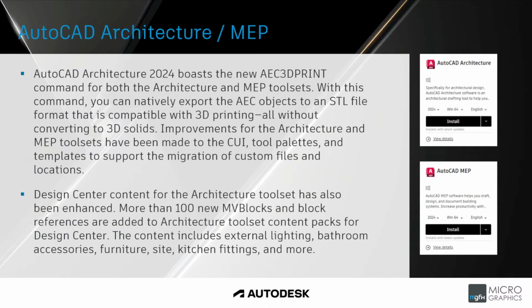AutoCAD Architecture and MEP. AutoCAD Architecture 2024 boasts the new AEC 3D Print command for both the architecture and MEP toolsets. With this command, you can natively export the AEC objects to an STL file format that is compatible with 3D printing, all without converting the 3Ds to solid.